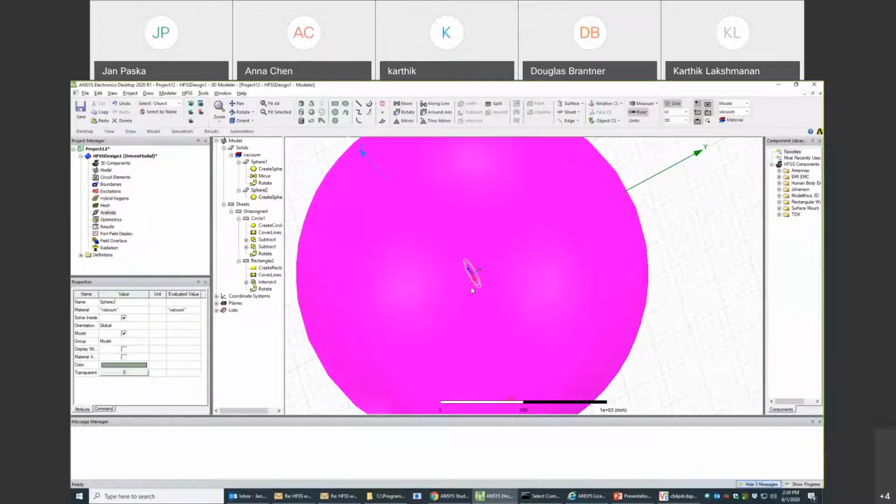So this is kind of an important thing. Right now we did only modeling. We modeled the things that we want to investigate, but now we need to add something that's unique to this software or unique to numerical computations. So we truncate the numerical domain. This we need to insert by ourselves. In this case, I chose a sphere. You could also do a cylinder, you could do a rectangle, whatever you want. But I chose a sphere.